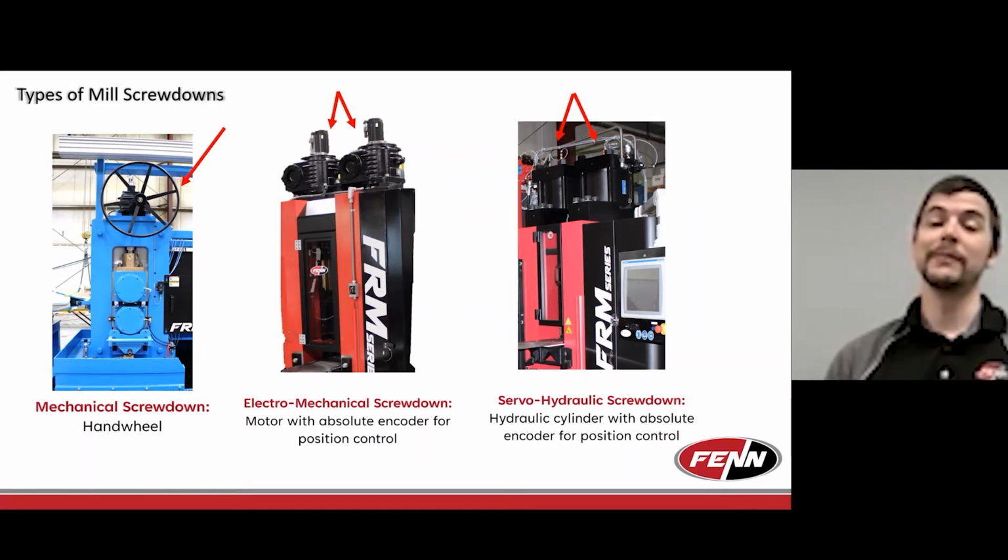That is more common on the continuous coil industry side, where you might need to make an adjustment while the rolls are already compressing material, and thus have enough torque to physically drive under load while the material is resisting it. With those 3 elements in electromechanical, you can make it do 2 of those 3 combinations with ease.